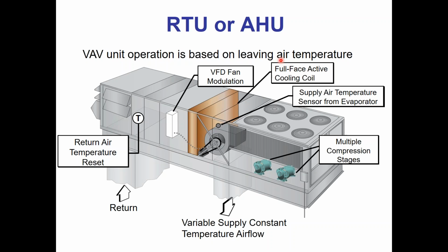So this only is going to be something you've got to pay attention to if you're retrofitting, converting something to VAV. I'm going to need the ability to measure supply air temperature. I'm going to be controlling to provide 55-degree air all the time. So if I'm doing that, I have to measure it. Otherwise, I can't do it. So I've got to have a supply air temperature sensor.